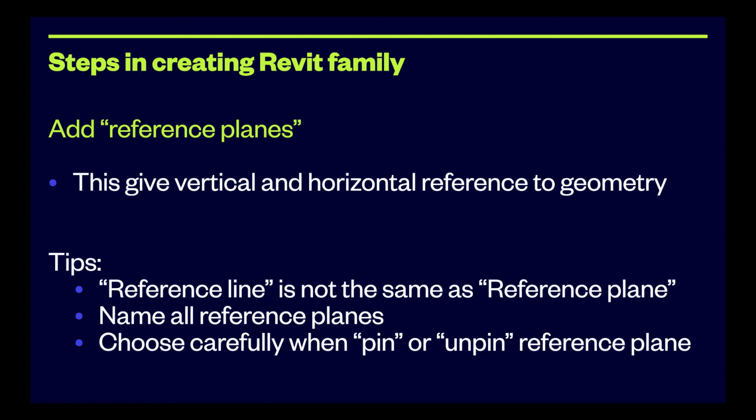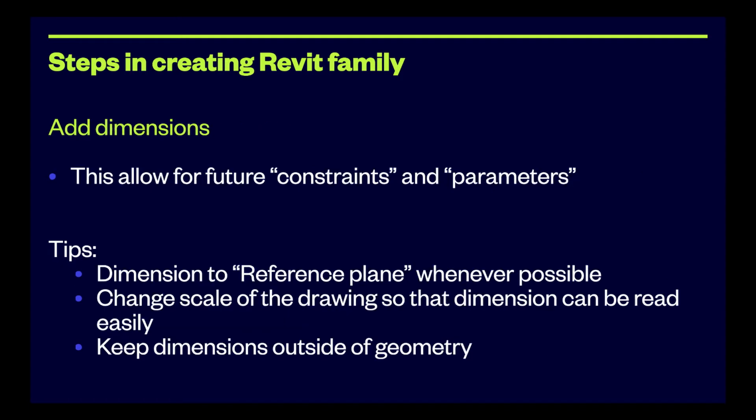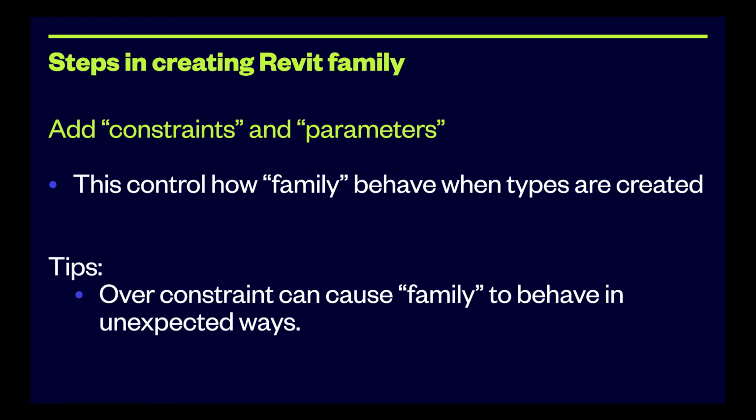Step 2, add reference plane. This gives vertical and horizontal reference to geometry. Step 3, add dimensions. These dimensions will allow for future constraints and parameters. Step 4, add constraints and parameters. This controls how the family behaves when types are created.